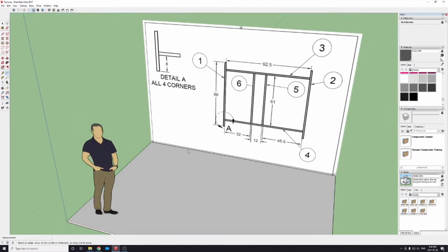There's a number of different ways that we can go about building this wall. We'll show you two ways, and I'll show you the first way as reference, but it's going to cause you a lot of problems in the long run. So we're going to create this wall section right here, and we're going to build off of that. First thing we need to do is define the size of our wood piece. I'm going to use the R key for rectangle, and I'm going to draw a rectangle, but I'm not going to click the left mouse button again quite yet.